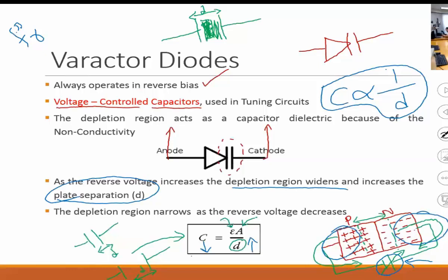When you push a button, the voltage is controlled, and internally the voltage controls the capacitance. So you don't directly control the capacitance. Now you can precisely control the capacitance, which helps you precisely tune a specific station. So a major application of this varactor diode is in communication applications, receivers especially, AM and FM radios, traditional communications.